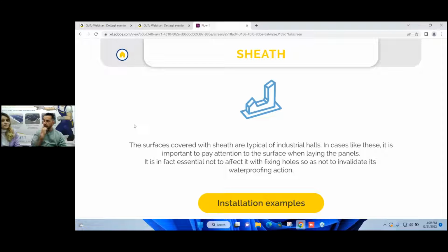The reason that I would highlight for this type of roof, for any kind of roof where Sun Ballast is used, is that you don't need to drill the roof. Correct. The shoe will help you protect the roof. Definitely, we don't want to make holes in the roof due to water, due to heavy rains. You know, water can go down. That is one of the main advantages, because you don't need to drill the roof. You can just implement the ballast directly.